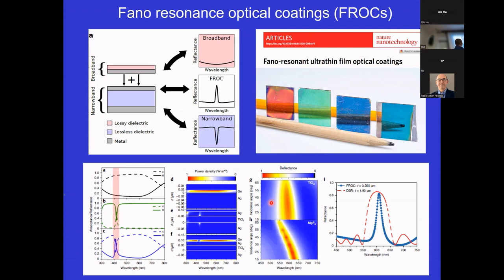And the bottom, the narrowband absorber, this is easy, right? A laser cavity, Fabry-Perot, is a narrowband absorber. So some type of this MDM, metal dielectric metal layer. Okay? So we put this together, and then we got this final resonance layer. So here's some simulation. And then what you see is a narrow band reflection.